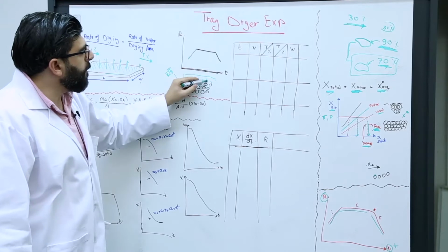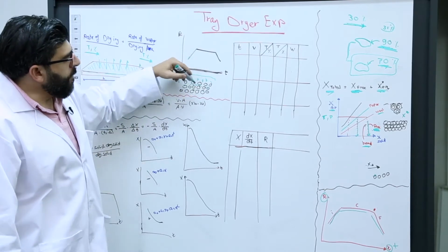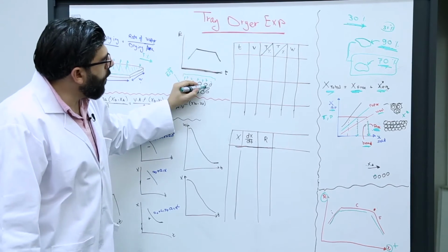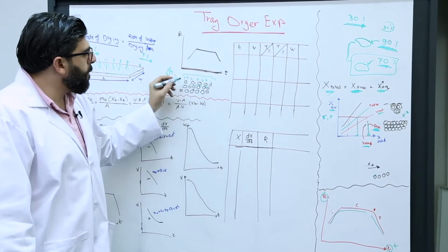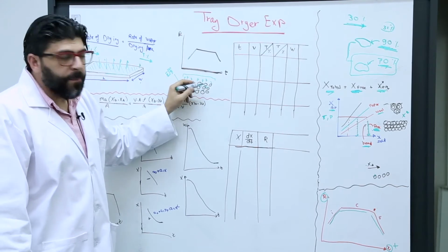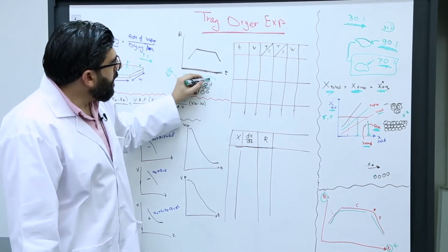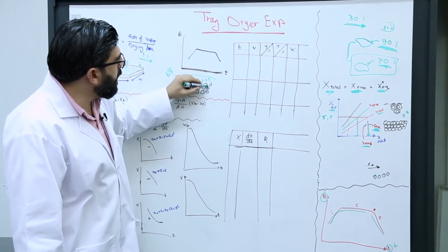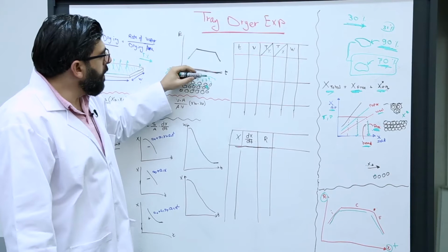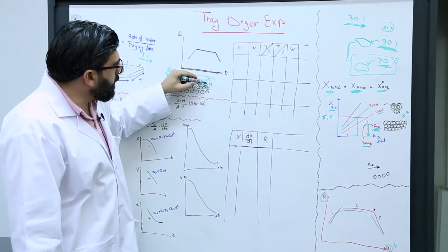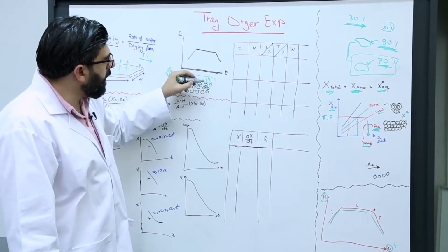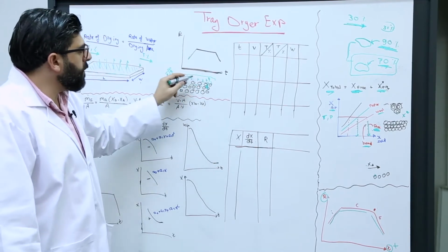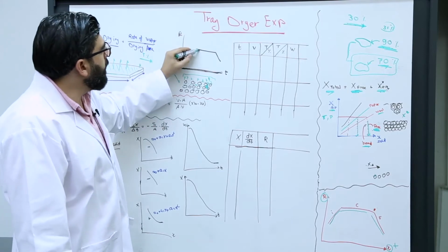And when the vapor moves to the atmosphere, it will be compensated by other water, because when you have a pore, we have like a capillary tube. So when vapor moves out, it will be compensated by another water from the sublayer. As water on the top surface vaporizes, other water will replace it, and so on. So the surface will be constant, so the drying rate will be constant